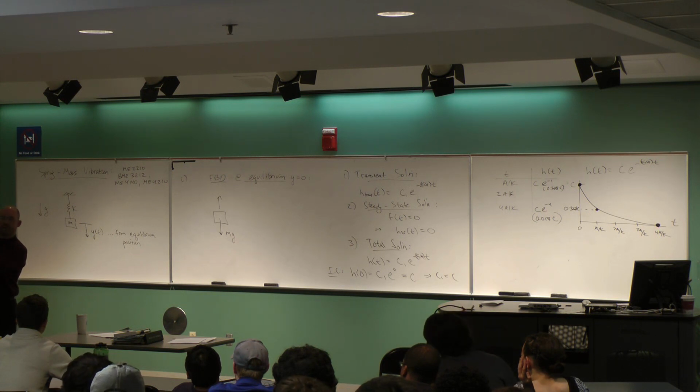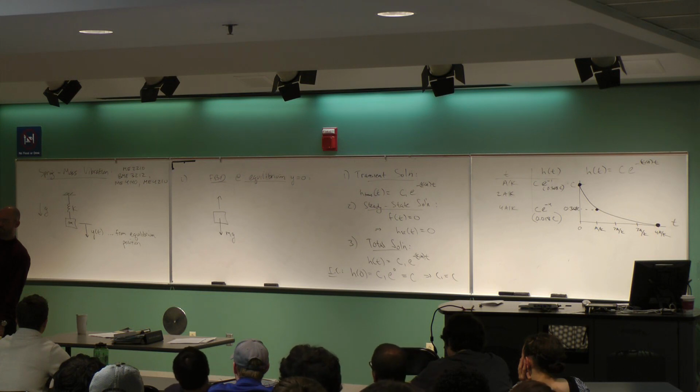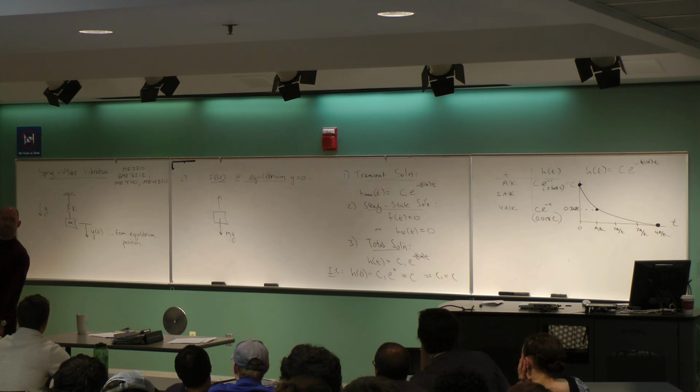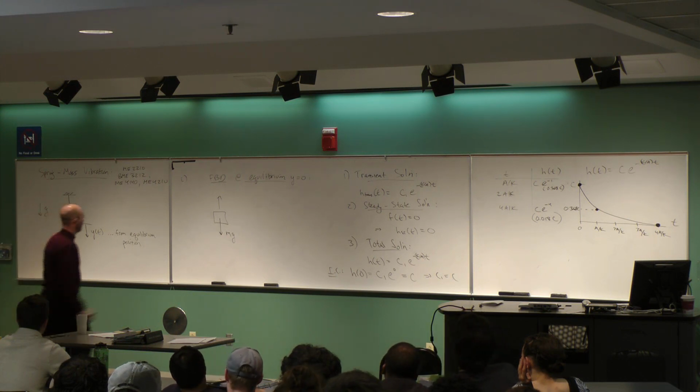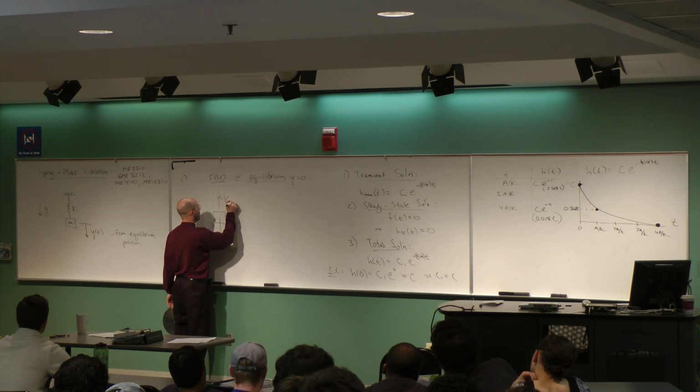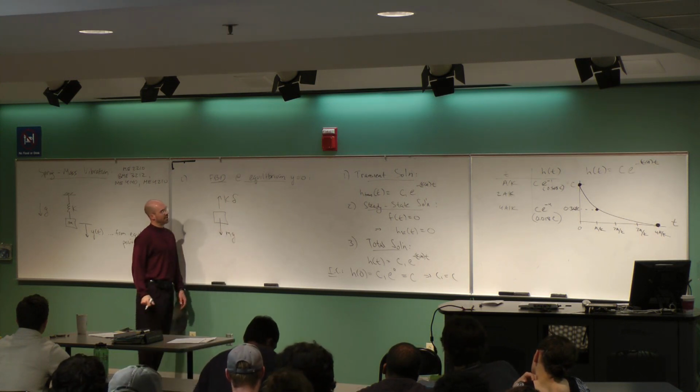So here we go again. Undeformed. Now it's deformed by an amount delta, and the delta is just enough to hold it up. So what's the force in the spring? Delta times k. Spring force is just k times the deformation. So I've got k delta in the spring. So k times, I'm going to use that Greek letter delta.